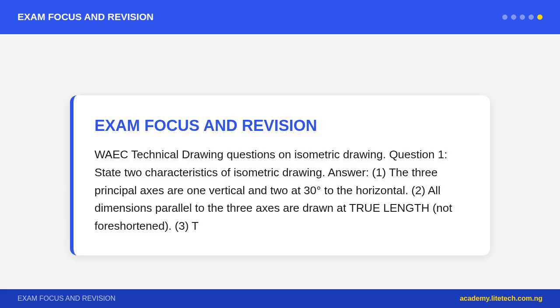Question 4. What are non-isometric lines and how are they drawn? Answer. Non-isometric lines are edges of an object that are not parallel to any of the 3 isometric axes. They appear at angles other than vertical, 30 degrees left, or 30 degrees right on the drawing. They cannot be measured directly in isometric. To draw them, locate their endpoints using isometric coordinates, find where each endpoint is along the 3 axes, plot both endpoints, then connect them with a straight line.